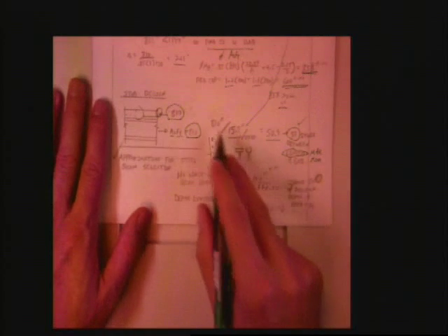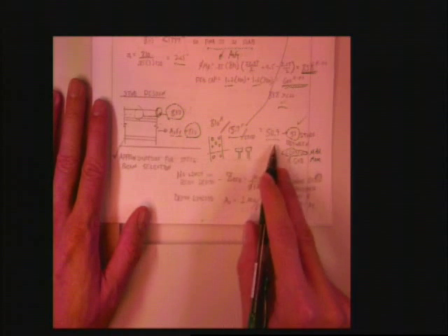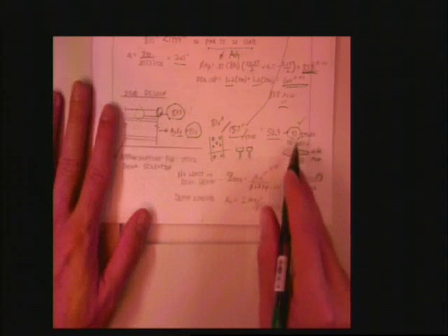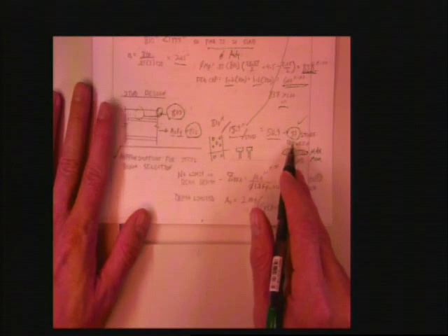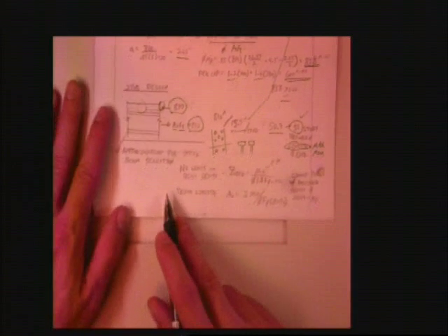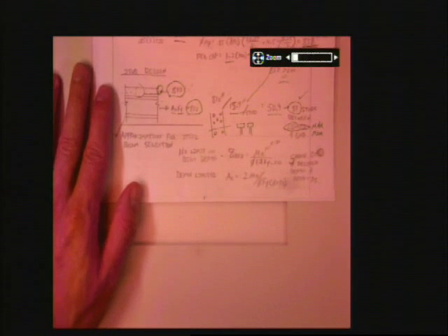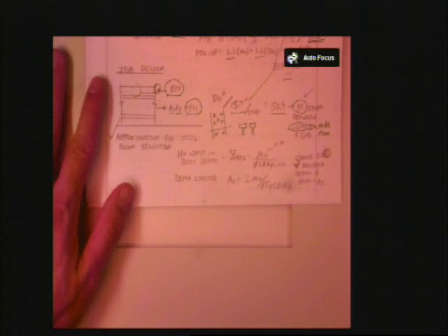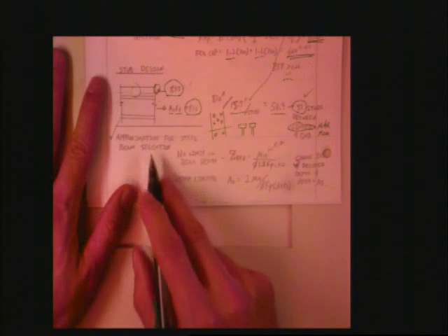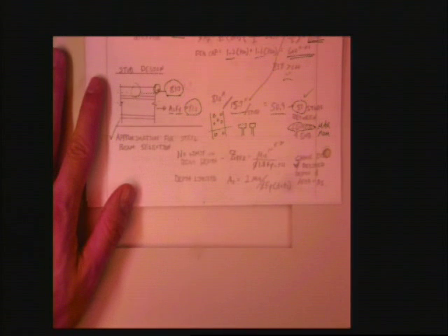So then I took 810 divided by 15.9. I got 50.9, rounded up to 51, and that's what I need between my max moment and my end. Okay, great. Now, these are some crazy, crazy useful equations. Approximations for steel beam selection.